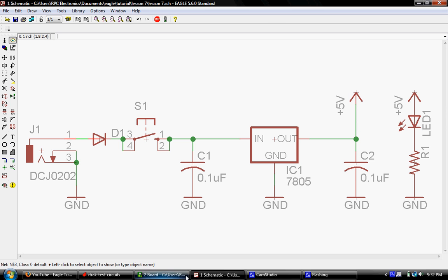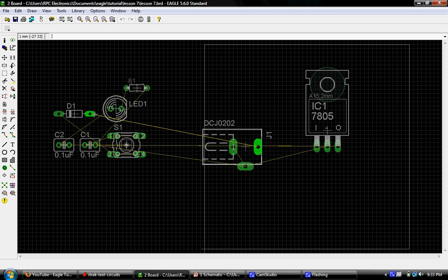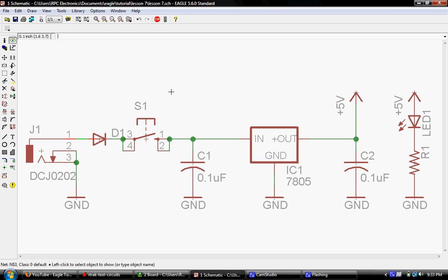Now, let's say I want to make this connection between the connector and the diode show up. I just click on that to highlight it, and now we can see that this pad and this pad are brighter, and the air wire is a little brighter yellow, indicating that particular connection. That's a very useful tool, especially when you get into very complicated schematics with multiple similar parts. For example, let's say you're working on something that has maybe 20 or 30 capacitors that are all the same, and you're trying to locate one easily. You can easily click on it with the show tool, and boom, there it is. You can see it on the board view.